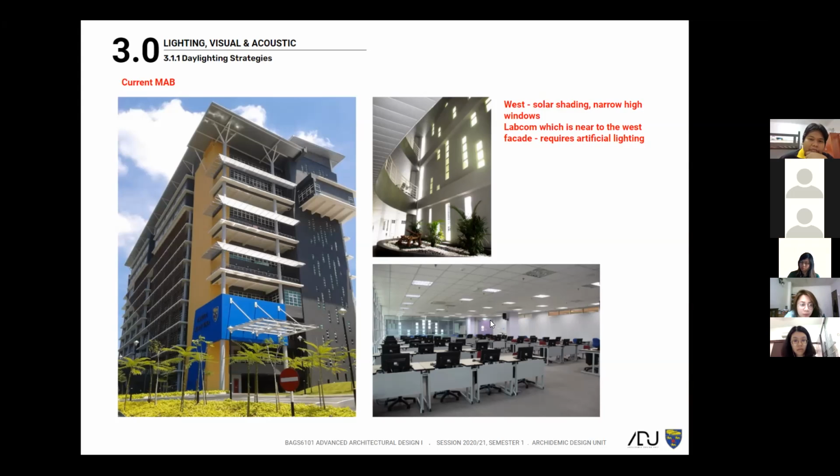So does that mean that's why they put the diagonal? There's this louver that looks like a diagonal thing. Yeah, all across. I think what you need to do is assess whether or not that works. Perhaps you can do a simple SketchUp model just to show how much shading you can get. Because there's a very deep overhang, about 1 meter deep. And then this screen is very cosmetic. It's not really a proper shading device. So it'll be interesting to find out how much shading you can get, especially from the deep 1 meter overhang.